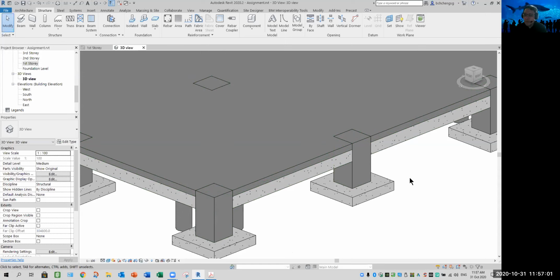But if you create something which is precast, or the material is precast, you need to draw precisely, meaning what? Stop exactly where it is meant to stop. You cannot create overlap. Not allowed. Okay, so when you're doing a structural model or doing structure for calculation, those guys, you need to understand this logic here in Revit.